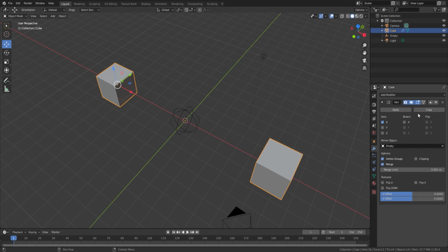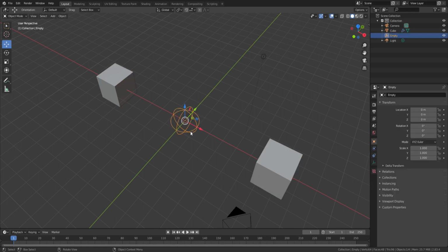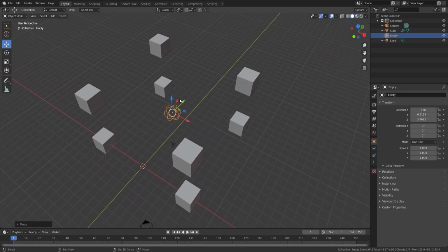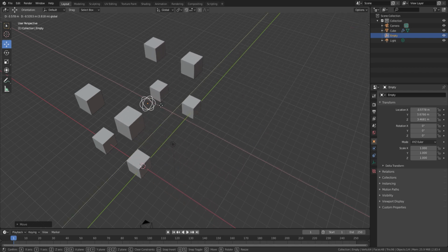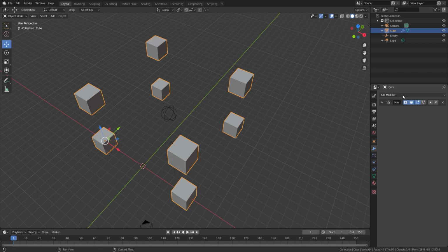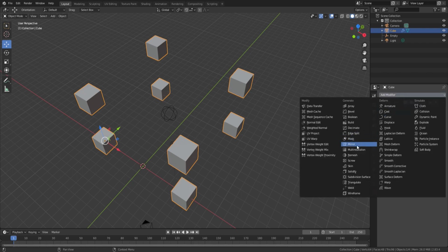The mirrored clone is visible only on the y-axis because the empty object provides us the axis of the mirror, so we can shift it away. So now the clones are visible. With this you can create interesting animations by using keyframe. Of course you can add further mirrors to this which duplicate the previous levels.